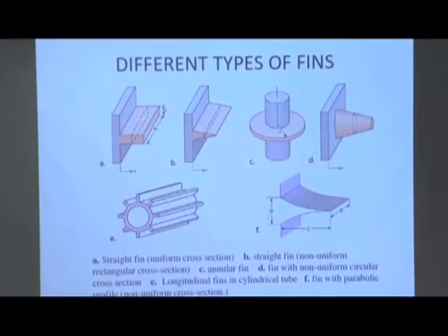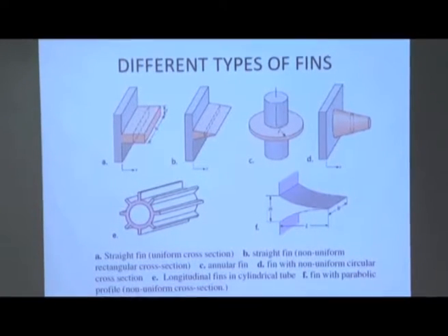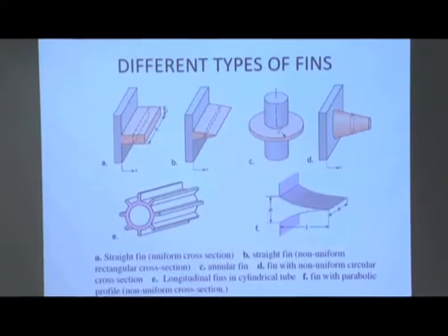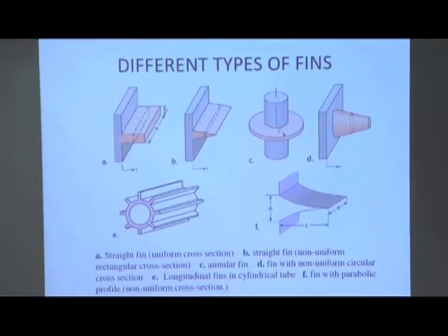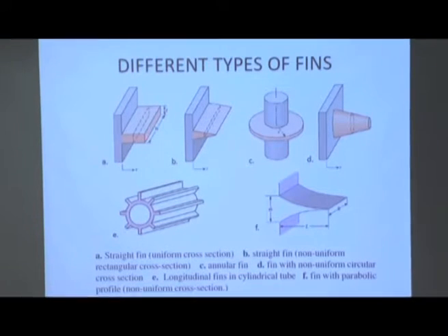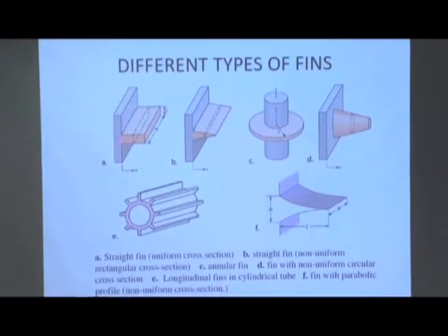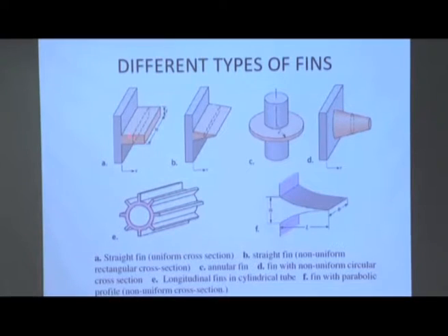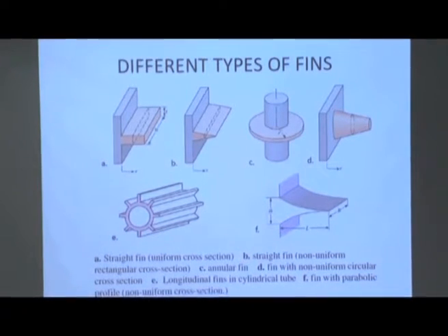This top, bottom and lateral surface, all these are additional surfaces for convective heat transfer, along with the conduction through this fin along this direction, by which the heat transfer from the base surface where it is attached is enhanced. This was discussed, and from the conservation of energy principle we developed the differential equation for temperature, and we solved it under different boundary conditions, different situations.